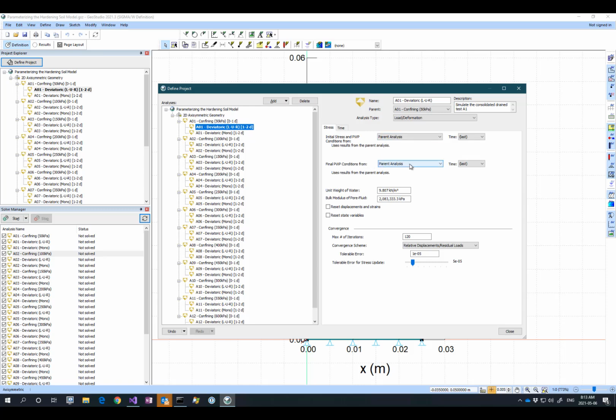Had these been different, due to, for example, specifying the pore pressures from another GeoStudio analysis like Sigma or SEEP, or the use of a water table or a spatial function to define the pressure heads, then that change in pore water pressure would be reflected in the simulated deformation response of the specimen.